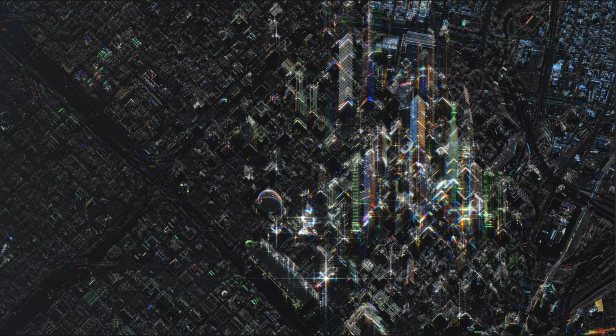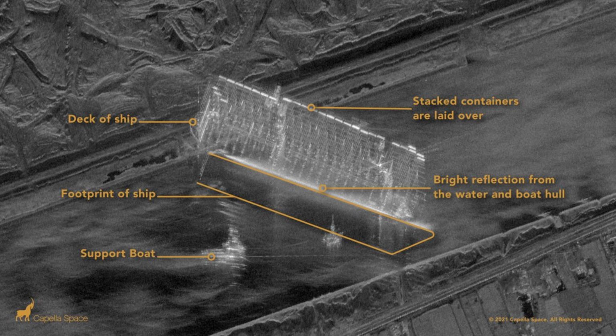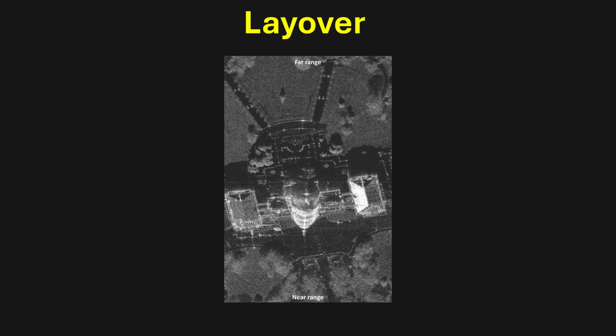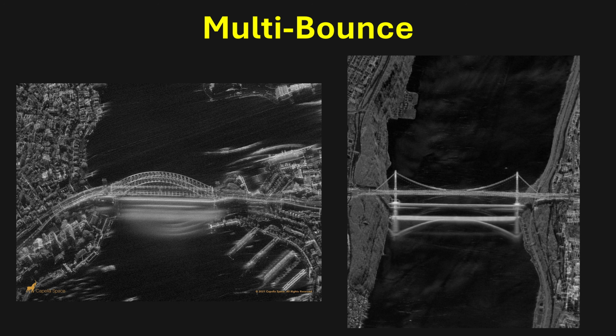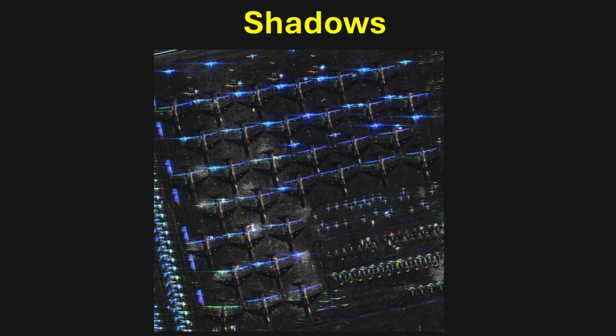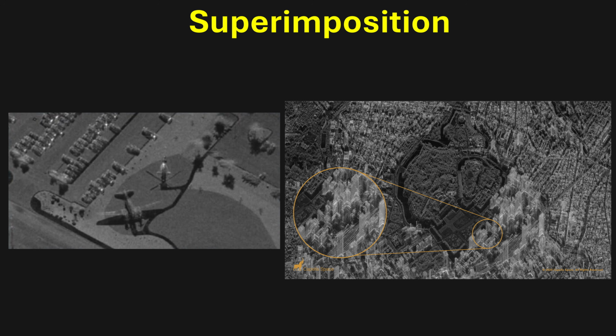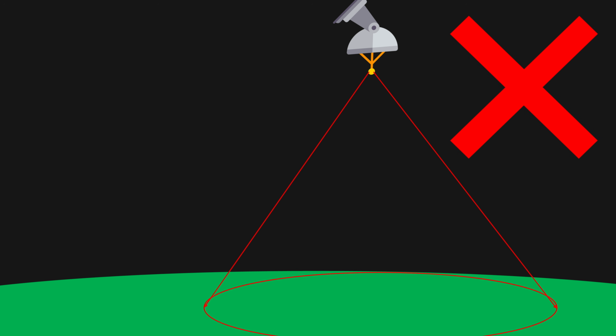Using range as an axis of an image is why SAR images look so strange compared to photos. Here I will show examples of the so-called artifacts that this produces. Image formation with range and azimuth axes is also why SAR platforms usually only work at grazing angles between 30 and 60 degrees. If you try to use SAR directly above the target, all of the ground clutter will fall into the same range bin and you will not be able to resolve the scene.